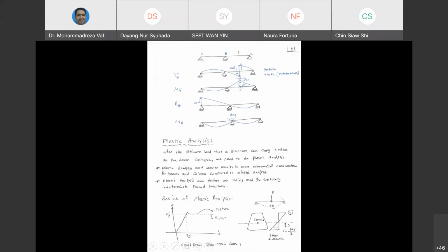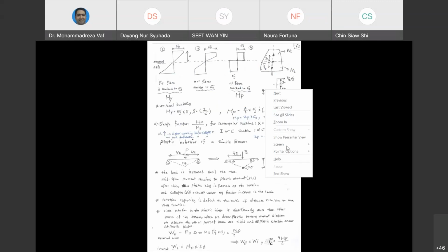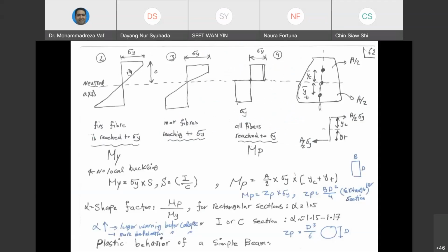And then we said if you increase the force in the beam little by little, more and more fibers are going to reach higher stress until the last fiber on top or at the bottom reaches the yield stress. The moment you reach the yield stress, the stress is not going to increase, because according to the graph we just saw, by increasing the force, only the elongation inside your fiber is going to become larger. So at this time, we have reached the yield moment of our cross-section.